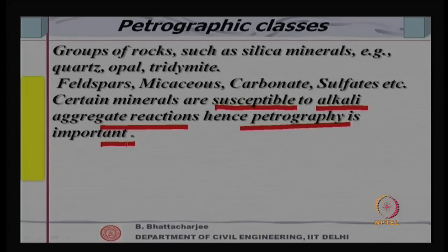Because of the durability issue, petrography is important when an aggregate is used for the first time. If it is a proven aggregate, it has been used in many structures and did not exhibit any sign of deterioration or alkali aggregate reaction over many years, then of course, we are sure of it.